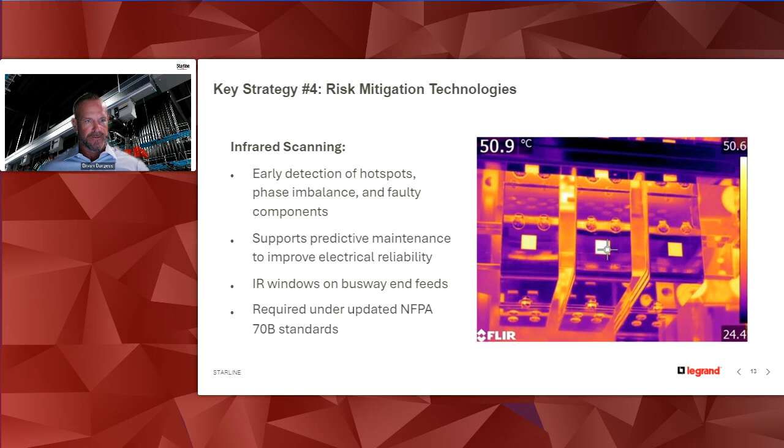So you've got those 3 bus bars. The cursor can be programmed to either find the hottest spot in the image on its own. When it does that, it'll indicate that temperature at the top left there. If not, if you want to pinpoint it, the technician wants to say, hey, I want to see this particular spot, then you can set the cursor where it stays in the center, and then it points the camera and it'll give you the temperature.